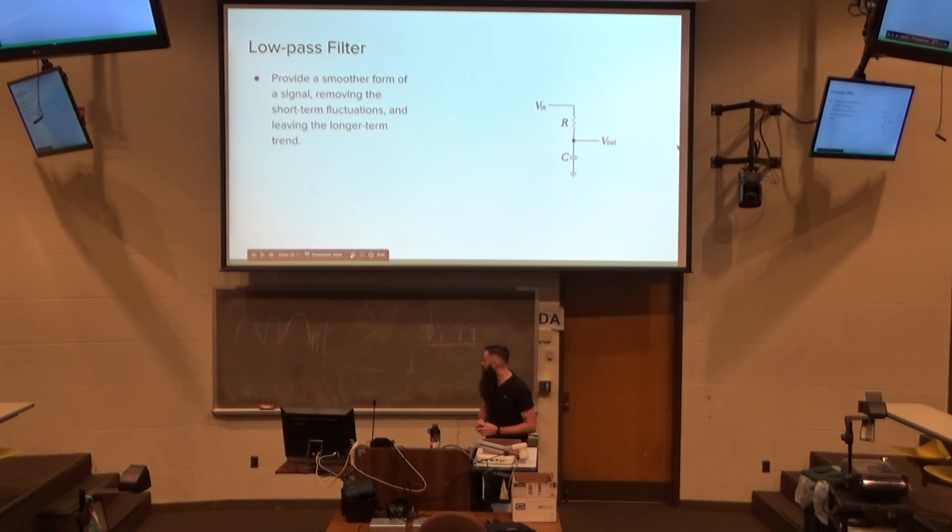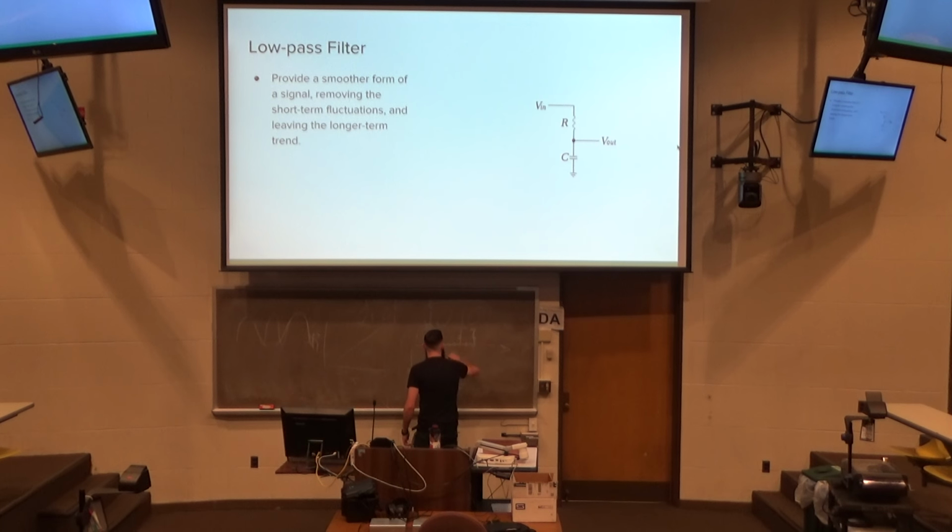And what happens is that you take your pulse width modulated wave that looks like this, and when it spits out the waveform, it curves it exactly like you want it to. This is a really bad drawing, but it curves it exactly like you want it to by attenuating the wave as it goes, and it just perfectly smooths it like you would want it to. The higher quality your parts here, the better it's going to smooth the wave. That's a whole other thing, and it can apply other types of distortions we are not going to talk about because they're way worse.